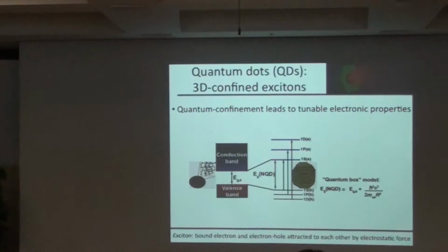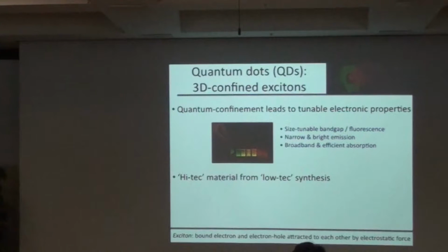In the case of an infrared band gap bulk material like lead selenide, we can actually tune from about the near infrared of a micron to even 4 microns, so all the way fully into the mid infrared. So the same composition, change size, change semiconductor, change color. And so what can we achieve? We achieve fluorescence that's very efficient typically, that's narrow band and bright. Absorption is broadband, and so these particles have a large absorption cross-section and they're easy to excite.